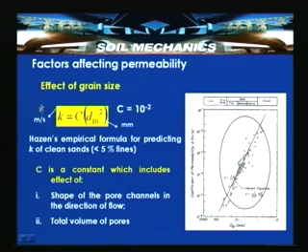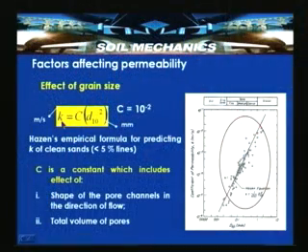So, this is a very important equation for determining the coefficient of permeability based on the particle size distribution. This is one of the significances of the particle size distribution we discussed while covering the sieve analysis of soils. Here Hazen's empirical relationship is shown, which is k is equal to C D10 square, where C is a constant obtained from this regression. The zone circled and highlighted here shows silt and sandy particles, which is where most of the sample points are.